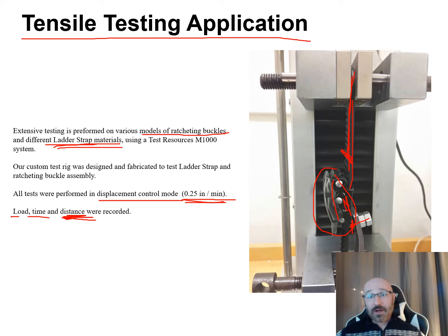So from that, we could then create our stress-strain curves, back out modulus of elasticity, look at our elastic limits, all those things that we saw in the previous graph. But again, be cautious, because we recorded load and displacement and we want stress and strain. So make sure we apply the right calculations, the right cross-sectional areas, and understand what the original length and the deformed length delta are to plug in to get the correct stress-strain curves.